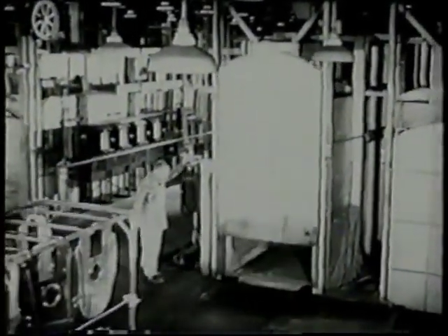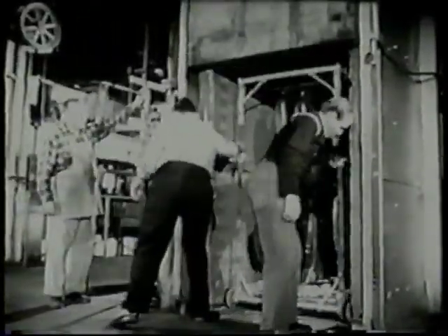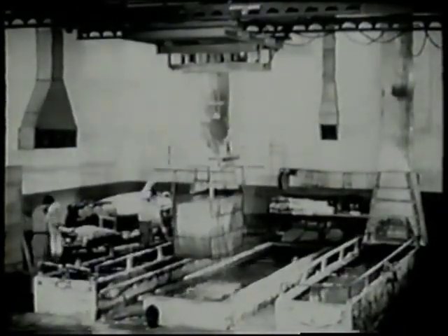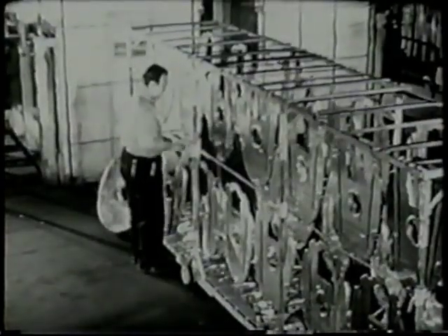The first stage in heat treatment procedure consists of a heating operation followed by a quick quench of the alloy part. Two different types of heating and quenching equipment may be employed in this process. The alloy part may be heated in an air furnace or in a salt bath furnace. Rapid cooling of the part may be accomplished by means of a spray quench booth or a quench tank.